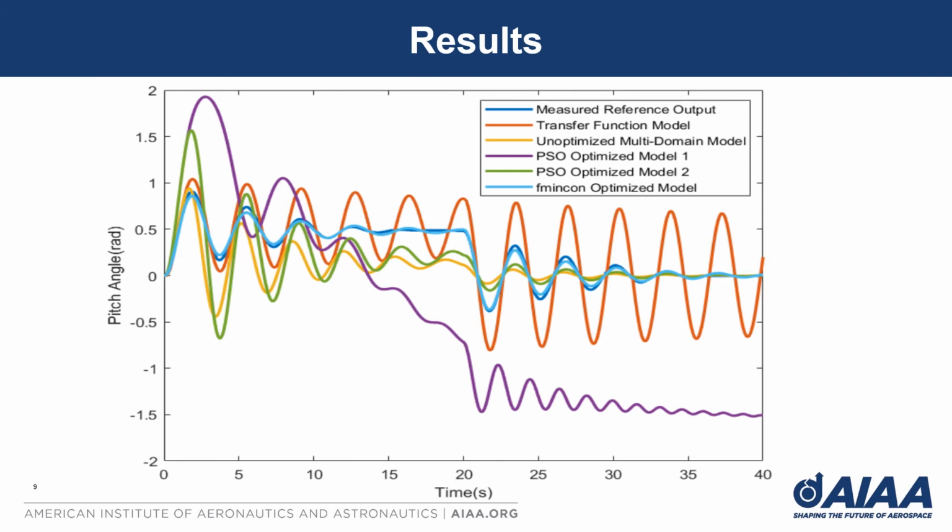the rotor and stator inertia of the motor, and the aerodynamic drag and thrust coefficients of the AERO. The electrical parameters were optimized using the current through the motor as the measured output data, the mechanical parameters used the mechanical speed of the motor as the reference data, and the aerodynamical parameters were optimized using the pitch angle of the AERO body. For all experiments, the input signal provided a constant 24-volt input for 20 seconds before stepping down to 0 volts for an additional 20 seconds.